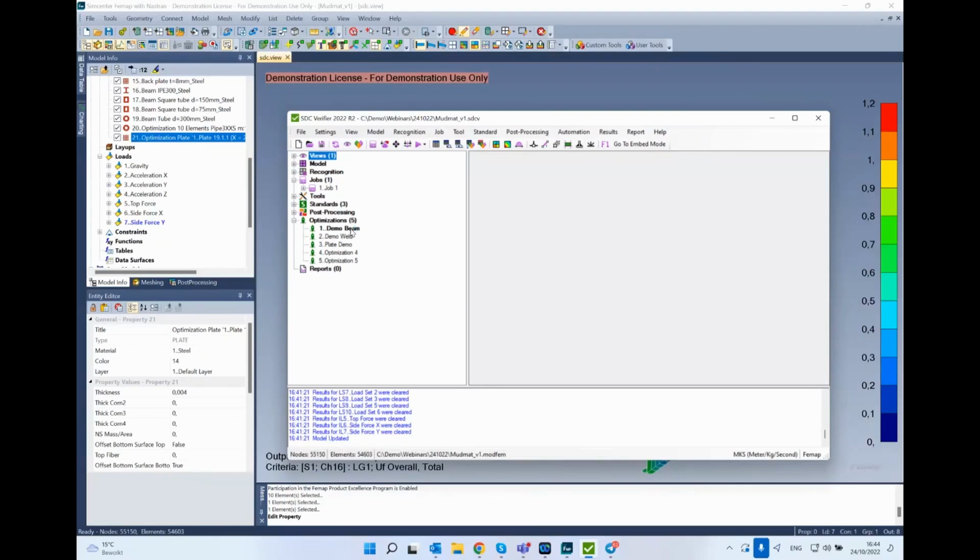Thanks. Okay, and also the question, does this software identify the conflicts between, for example, buckling factor and some stress utility factor, when we are reducing the plate thickness to reach some buckling factor, but at this time we are also exceeding our utility factor, for example, for a stress check?